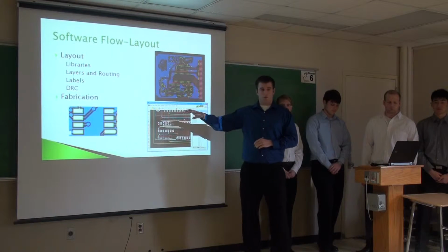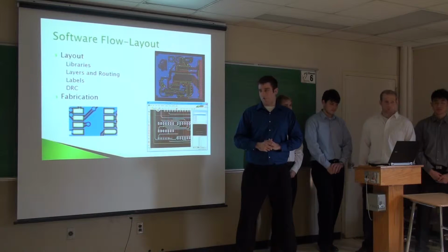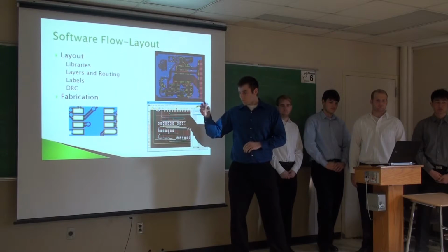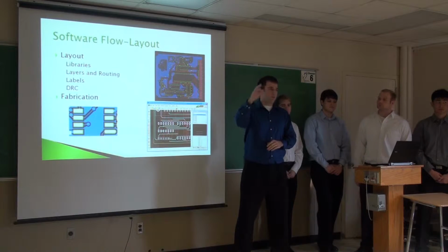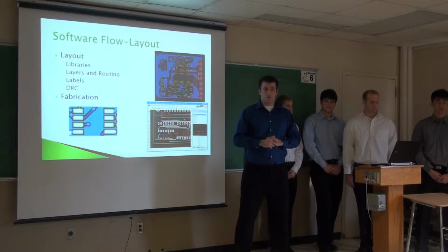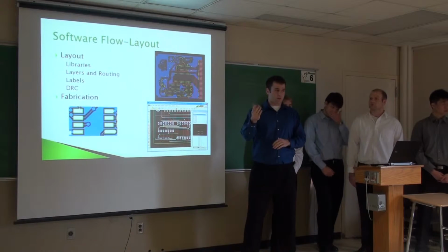So once you have all of your footprints in for all your custom ones, and the ones that are in the library will be exported, they'll come in, and you'll have your outline of your PCB board, and all the components will be off to the side. You can place them, of course, however you like. We'll go into more floor plan considerations later. You route them together. Routing, of course, is just adding the traces, which connect the pins.